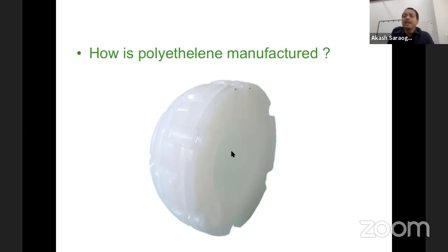First is that you have got fine powder. Now, this powder can be condensed to make this plastic. There are 2 or 3 different ways you can do it. The most common way is called ram bar extrusion, which means all you do is you take a mold, a big mold, and you put all this plastic, and under pressure, under heat, you make it into a bar. Now this bar you cut into pieces, you do machining and give it a particular shape. Now this is the most commonly employed method, and this is one of the worst methods to make the plastic. We still make plastics with ram bar extrusion.